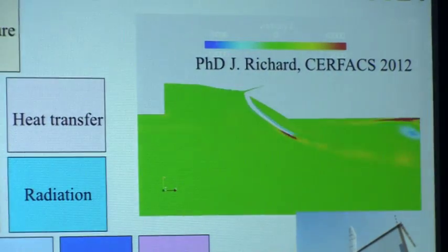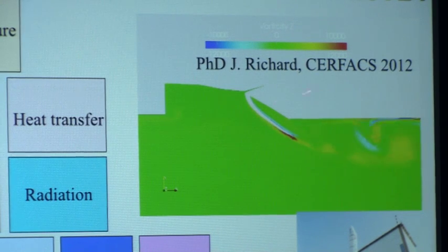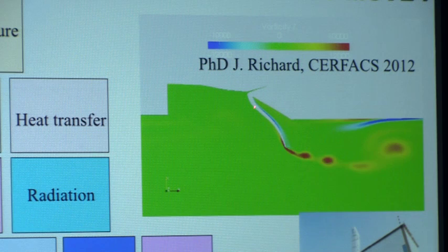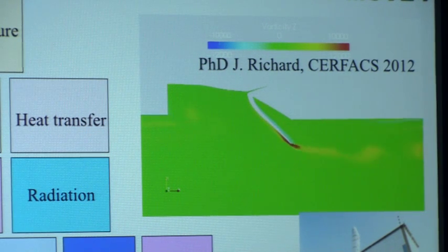Now, these structures may not have to be fixed. You can have vibration. This is in a rocket engine, for example. You can see this part here, which is a part of solid here. It can actually start moving. So that means quite often you have to care also about fluid structure interaction. Once you know the temperature of the walls, by the way, you look at the stresses there, and it could be also looking at the vibration of these things. So you see the picture becomes much more complicated.